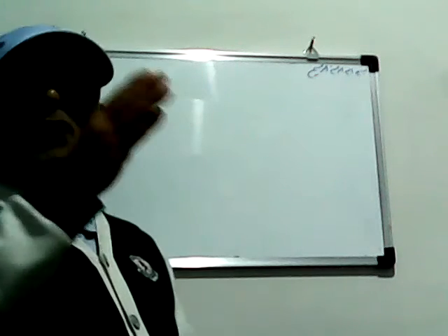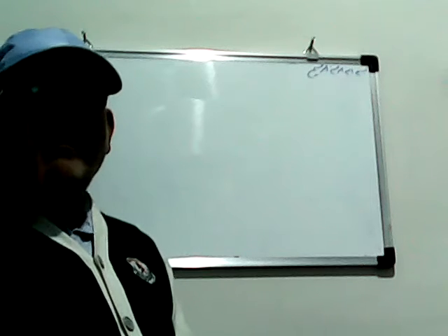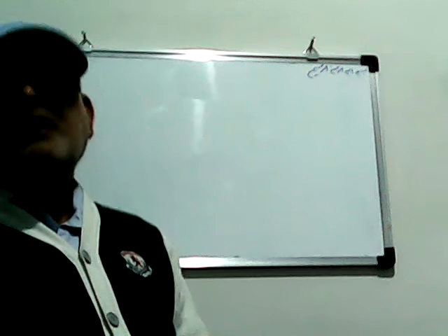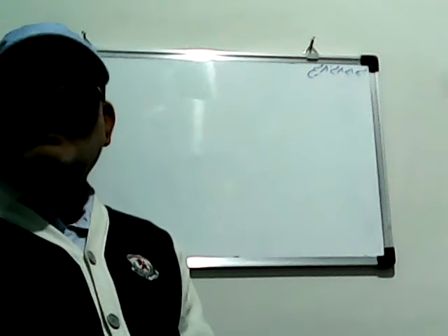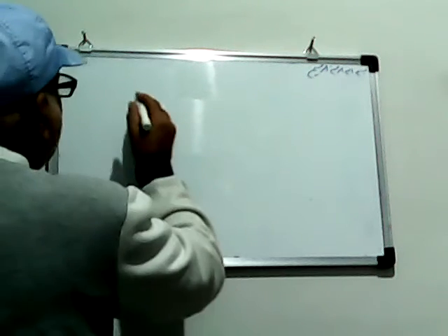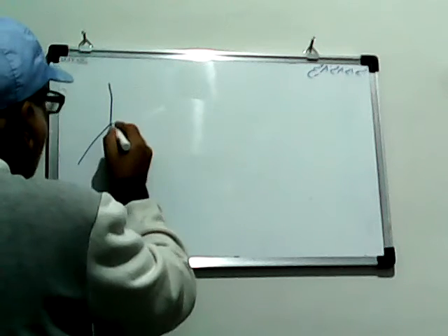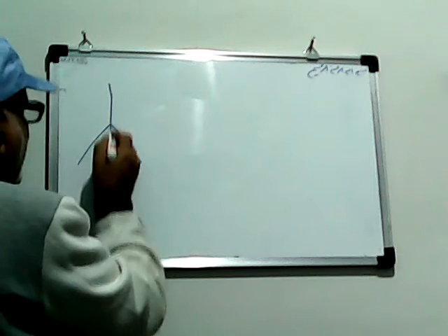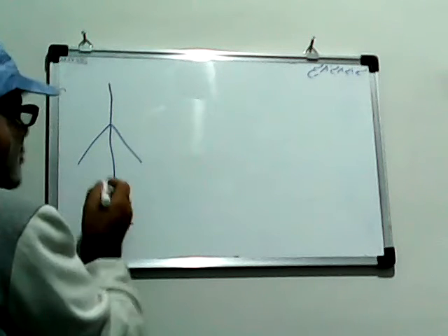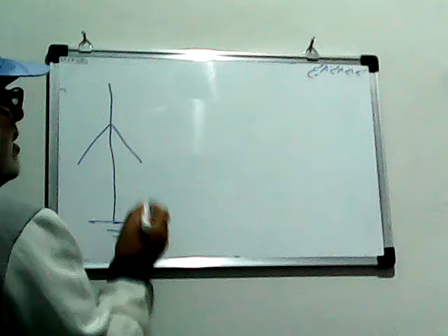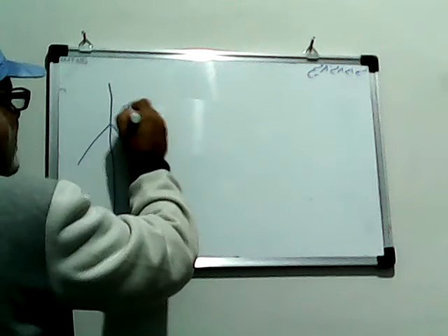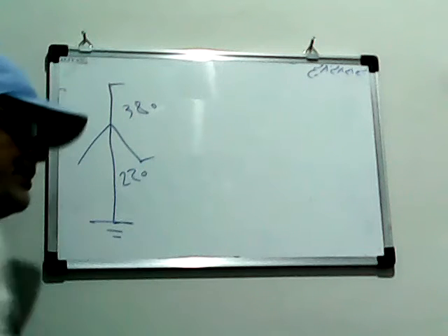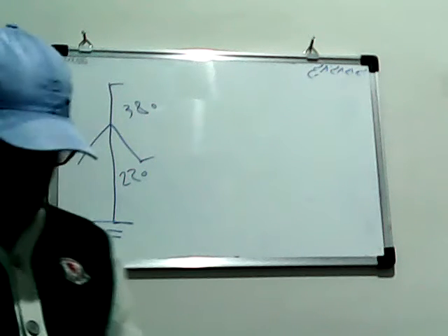The transmission is first 230 kV, 130 kV, 63 kV, 20 kV, then changed to 380 volt line to line and 220 phase voltage, here in Iran and some countries in Europe.